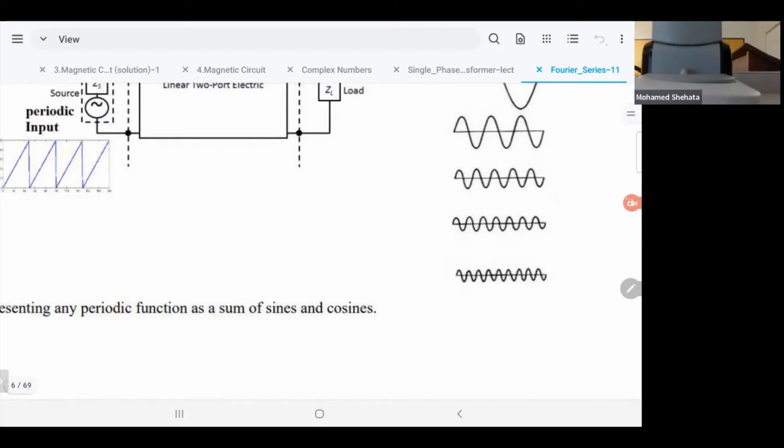So you have to know the amplitude and the frequency of each harmonic so you can design a filter to get rid of each component by the right amount. You can choose the elements of the filter in the right way to get rid of the harmonic. You don't oversize the filter.